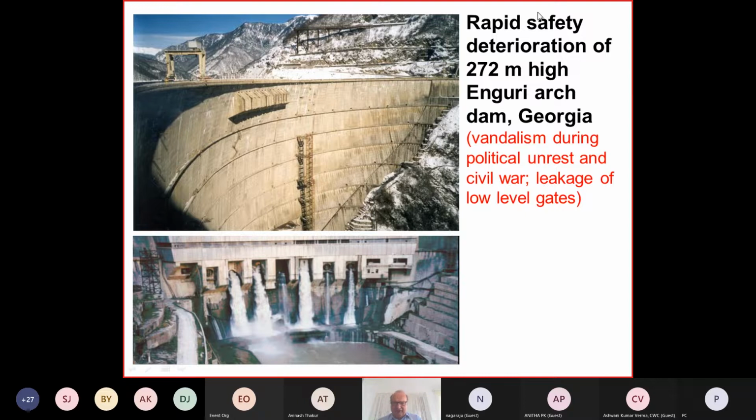An additional advantage: at the dam foundation contact, you have high tensile stresses on the upstream face of the dam, and by providing this joint, you basically eliminate these high tensile stresses, which have been a headache for some people for quite some time.